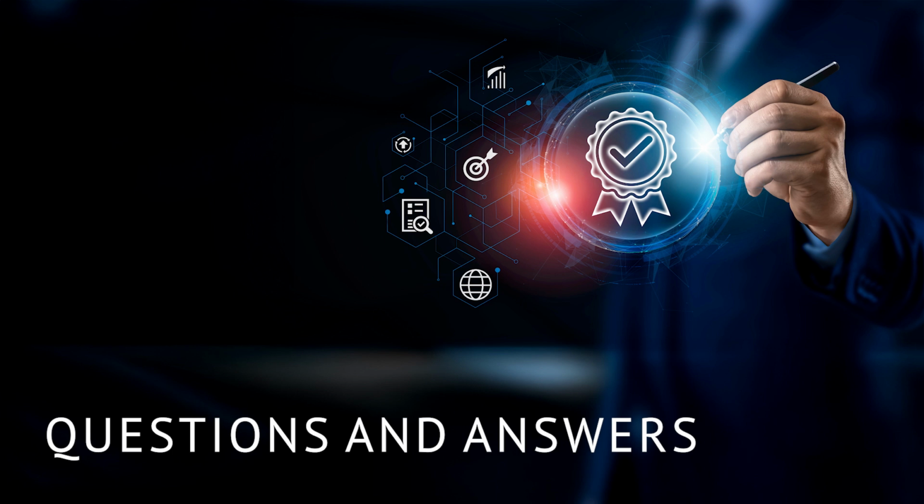So from a safety consideration point of view, I see within this the verification checks of the QSPI communication a huge safety improvement. And just an outlook, we also have the safety schematic package in our SafeTpal product portfolio, where we provide the reference schematic, which will help you to connect both chips, AURIX and the TLF watchdog, in a proper way